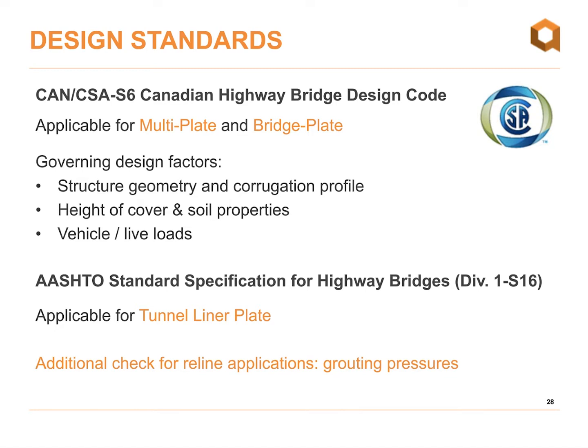Tunnel liner is actually designed according to the AASHTO standard specification for highway bridges. So there's no CSA standard that actually governs tunnel liner plate design. In a reline application, these systems are designed in the exact same manner as we do with a new installation. Of course, the key difference is that we are not backfilling it with a well-graded granular material. So instead, there's an additional check for grouting pressures. Very similar to checking for the backfill loads or construction loads of a buried structure during a new installation, we similarly need to check for grouting pressures at various states of the grouting process during installation.